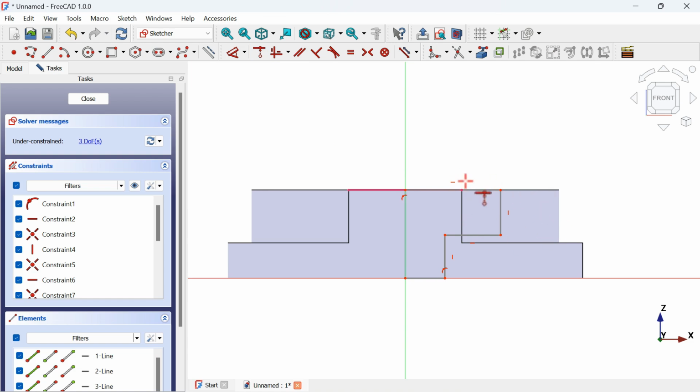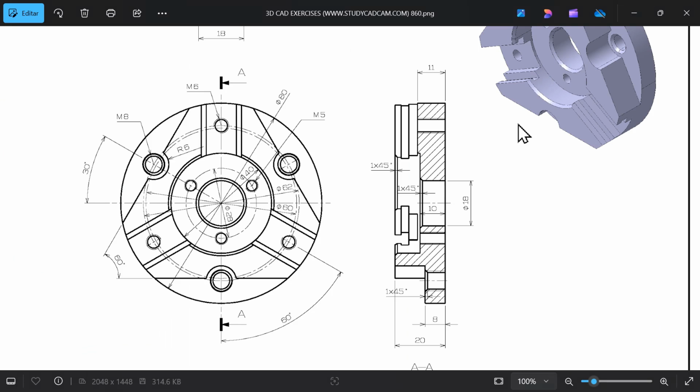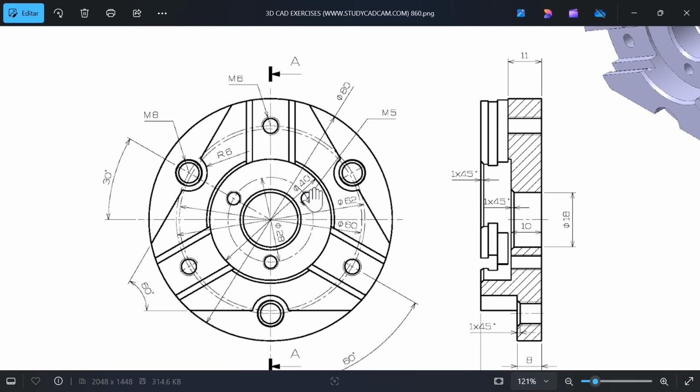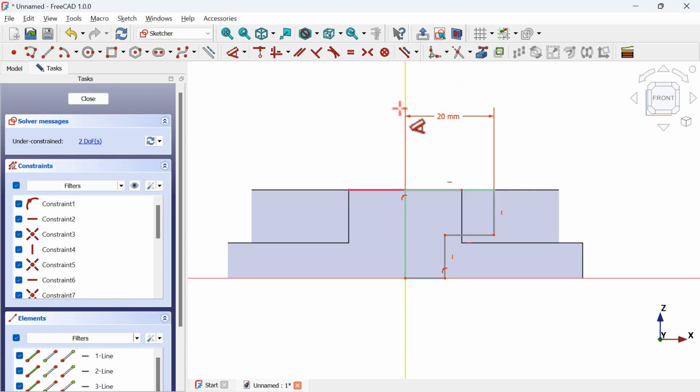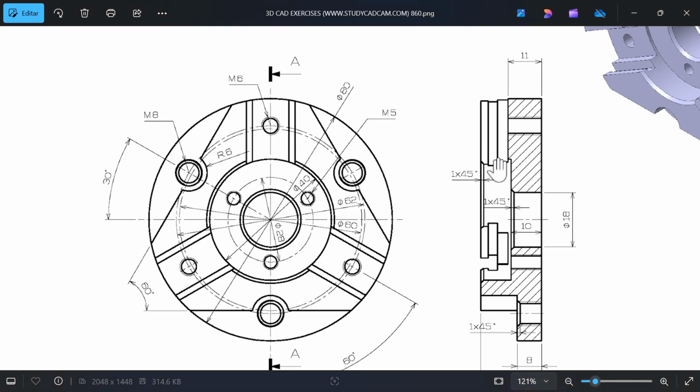Next, to set the dimensions of this sketch, we'll use the dimension tool. Just click on this icon and we'll start from this line here. Just click on this line and now click here. And as we can see here, we have a diameter of 40 millimeters for this circle, for this hole. What we'll do is to set 20 millimeters because we're creating a section of this hole.